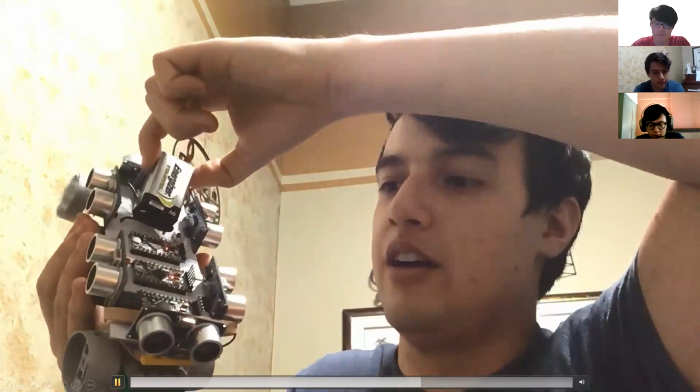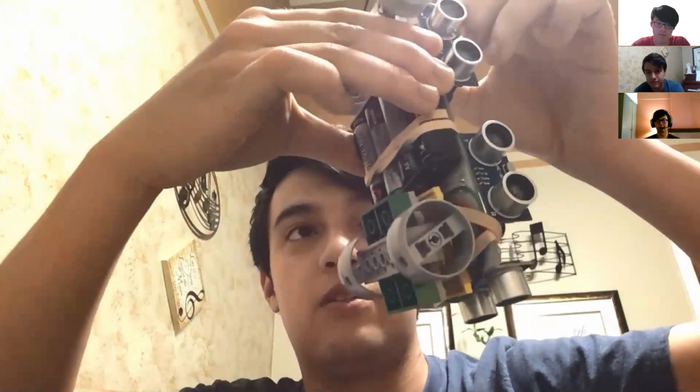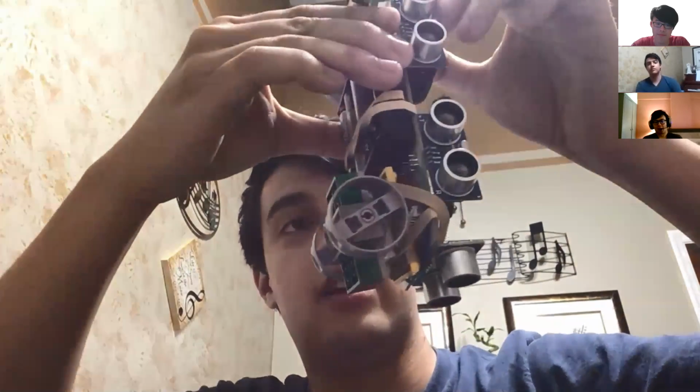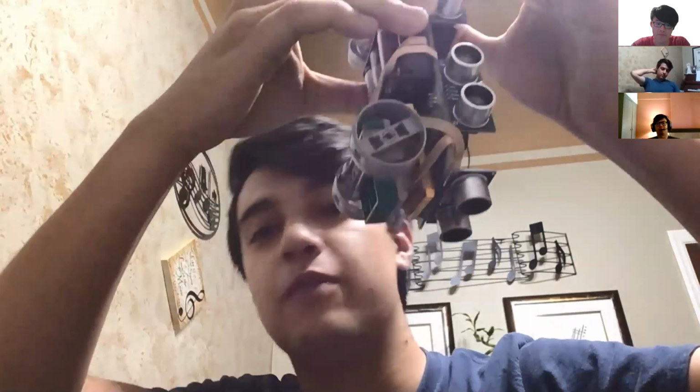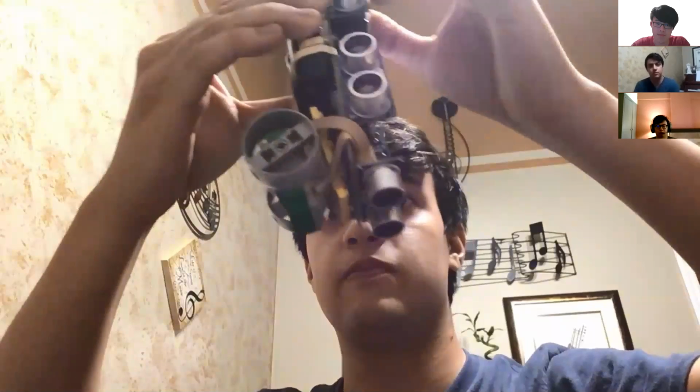So the 9 volt, it's really a parallel power system. If one fails, then the other will help it out. Just a little bit of troubleshooting there. The 9-volt battery supplies most of the power to the motor, and under here we have 4.5 volts, which supplies power to pretty much everything else. Since we use the raw input power for the Arduinos, we actually use both the 9 volt and the 4.5 volt, so if one dies, then the other will take its place and vice versa.